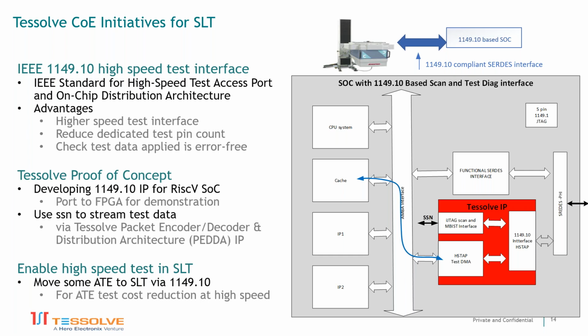A lot of the companies developing SLT, when they go to SLT for volume, want to move some of their structural tests into SLT, because they see SLT as something they need to have in order to get their fault coverage up. So it's something they need to do. And they're thinking, well, why don't I make it more cost effective by moving more of the structural test into the SLT environment?